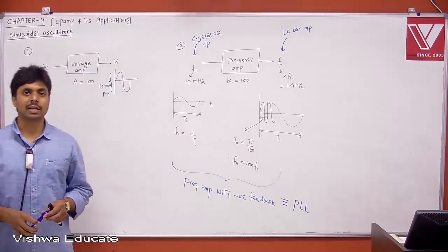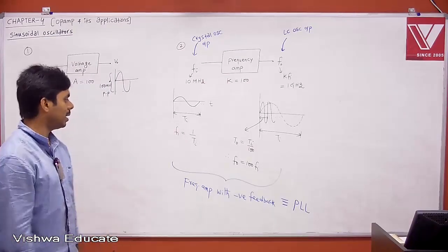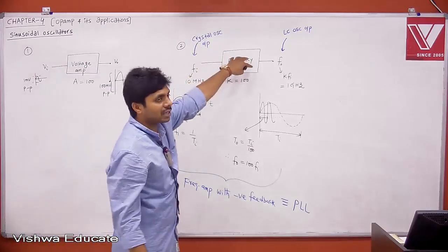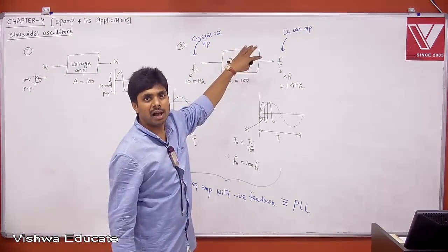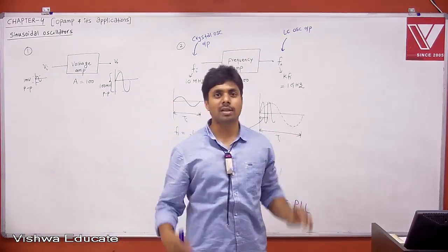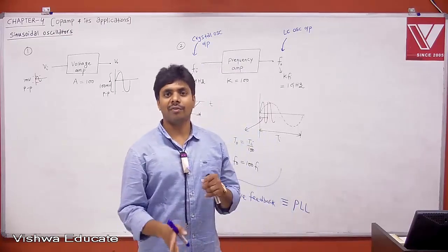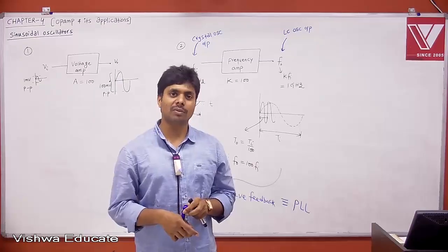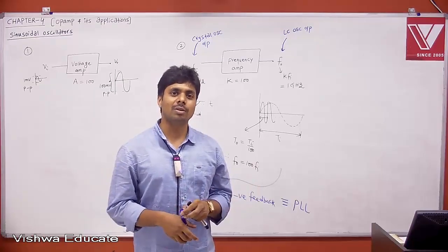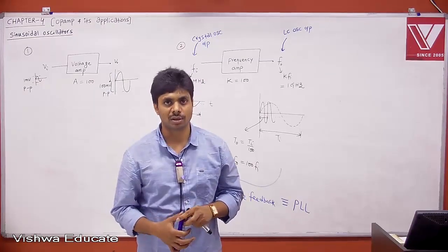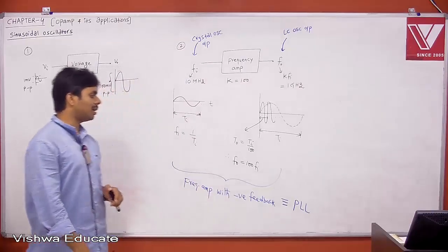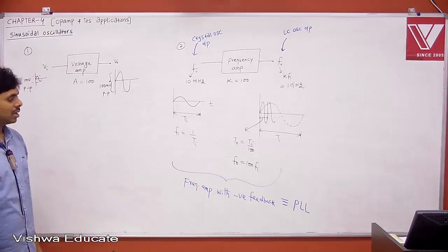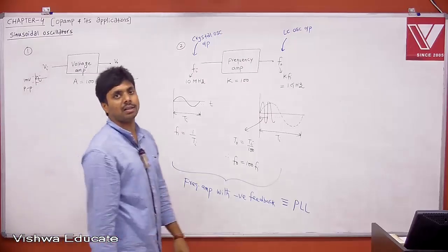This is what people technically call a PLL, phase lock loop, which has an LC oscillator internally, that is the core of your PLL, and the crystal oscillator output is the input to your PLL. We have a phase detector, divider, and error amplifier. The error amplifier is nothing but a low pass filter. Then finally it controls your output signal variations, okay? I'll explain the block diagram of PLL, and with that I will say your oscillations are over. A conclusion: remember, this is what people use practically.